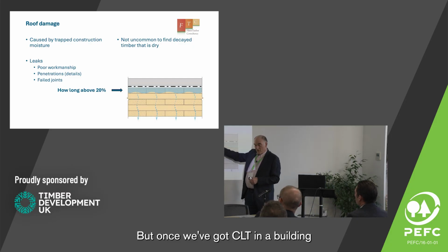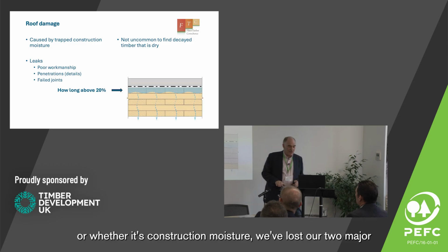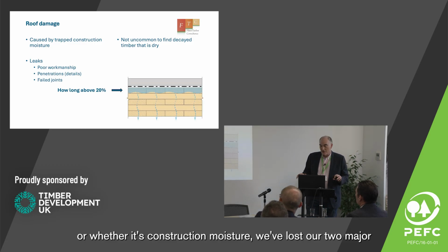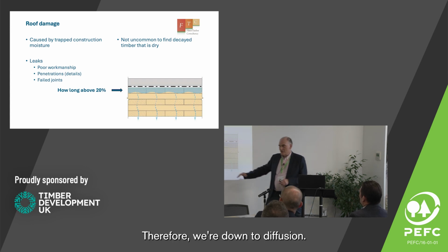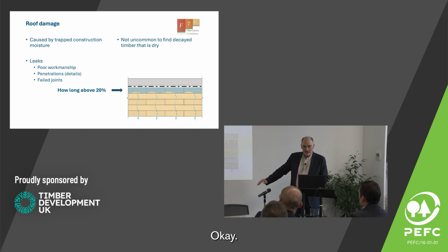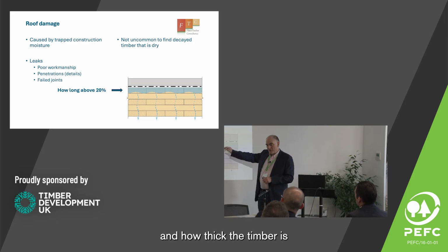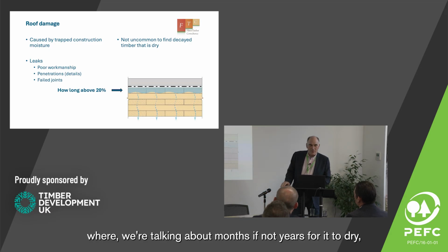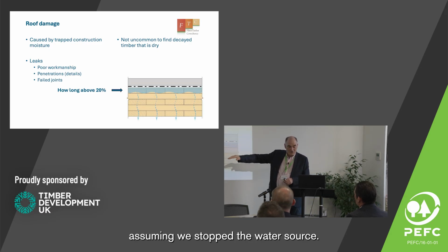But once we've got CLT in a building, and if it's wet, whether it's a leak or whether it's construction moisture, we've lost our two major forms of drying, which is drainage and ventilation, evaporation. Therefore, we're down to diffusion. Diffusion's a very, very slow process. Okay, so once this gets wet, depending how wet it is and how thick the timber is and how much is wet, we're talking about months, if not years, for it to dry, assuming we've stopped the water source.